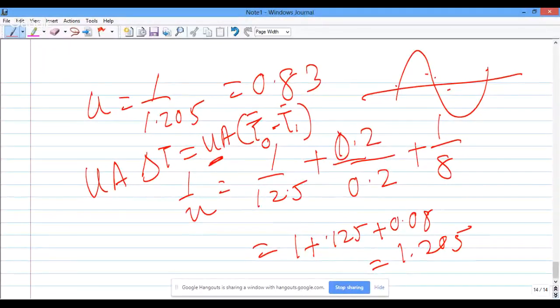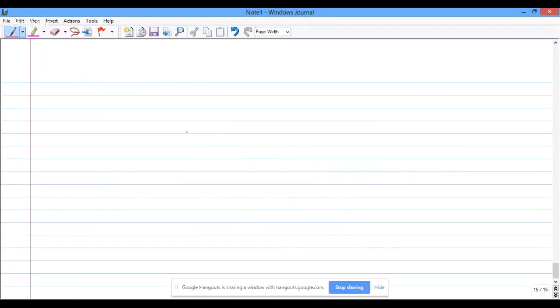And similarly, if I know the number of air changes, let me take up an example. Let's take the ventilation heat flow. And how do we calculate the ventilation heat flow? The simple approximate way is 1/3 N into V. That's what we have used most of the time. Actually, it is 3600 divided by 1300 or so. N is the number of air changes.